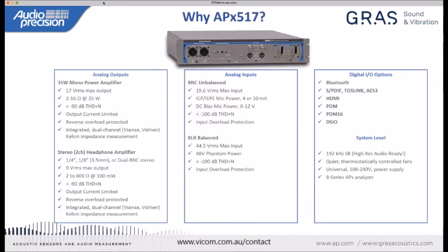And what we're going to take advantage of today specifically is, number one, there's a built-in 35-watt power amplifier. And maybe you'd normally think of that power amplifier as being used to drive a speaker that you're measuring. But today what we're going to do is use that power amplifier to drive a speaker we're going to use as the sound source when we want to measure a microphone.